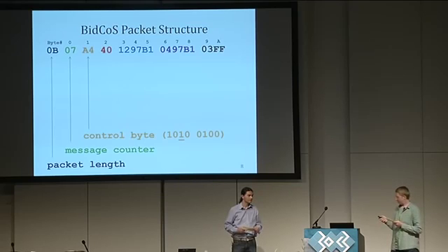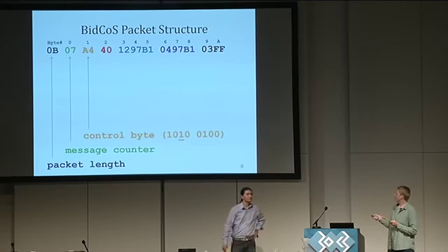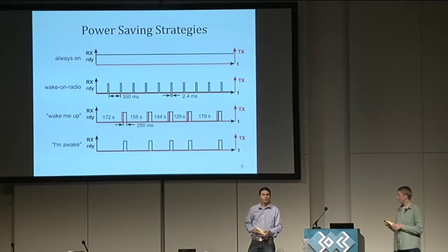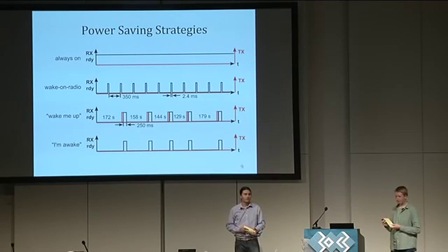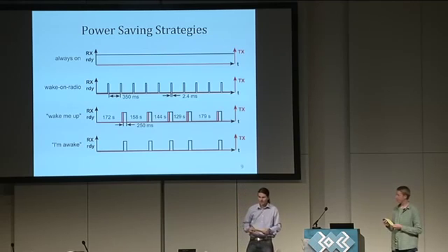Byte 1 is the control byte, which, for example, encodes the information here at bit 5 that the mode is used without a wake-up packet. This mode is used by a thermal control device and valve drive device.